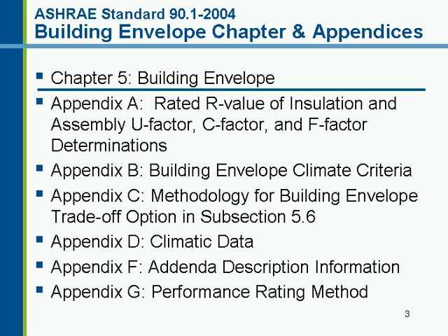And I wanted to point out that they don't exactly match up all the time one for one with what's in Standard 90.1. So for example, if you're doing trade-offs, the baseline for the wall assembly is a steel stud wall. So it doesn't matter if your proposed design is a mass wall, concrete block, something like that. You start with steel stud as the baseline for performance calculations. This is also another reference for you to be aware that there are envelope criteria in that.